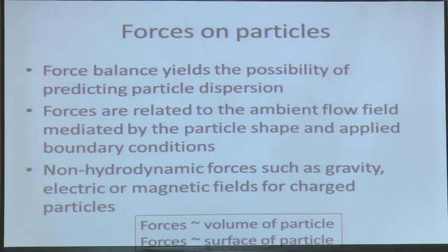It is proportional to the volume. And the second force, which is mediated by the fluid, is proportional to the surface. Okay, so as you expand the surface, you may have more stress due to the fluid. So you may have actually two contributions. One is pressure along the surface, and the other one is viscous stress. Okay, so as you increase the surface, you will increase the response of the particle to this flow.